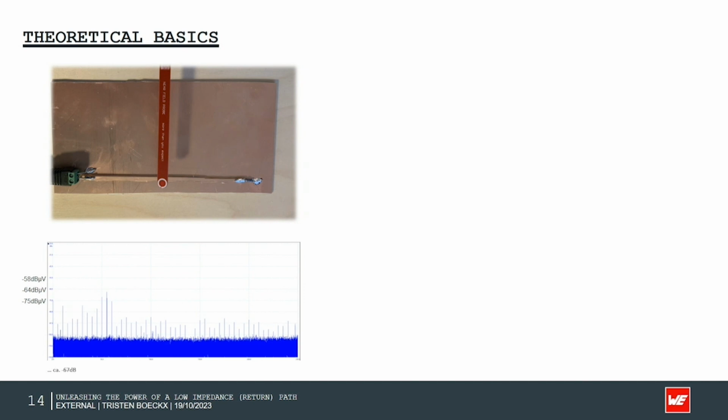If we start measuring at the edge on the top, we will see no signal. We will measure no signal from the signal trace. When approaching the signal or the transmission line, we will be able to detect the return current as shown below in the left bottom picture.